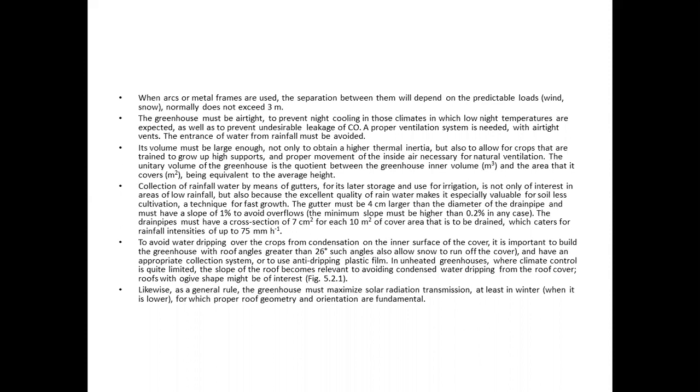Also, the greenhouse must be kept airtight and also insulated so as to avoid heat losses, and the CO2 leakage should also be prevented, so as to prevent the low night temperatures in the meantime. Also, a proper ventilation system is needed in the greenhouse.